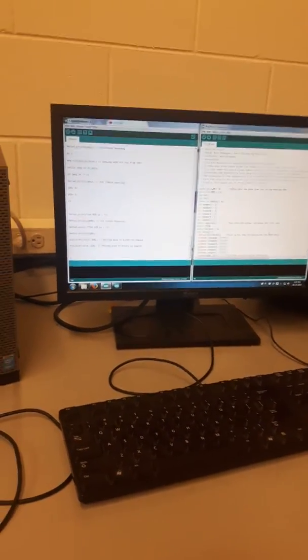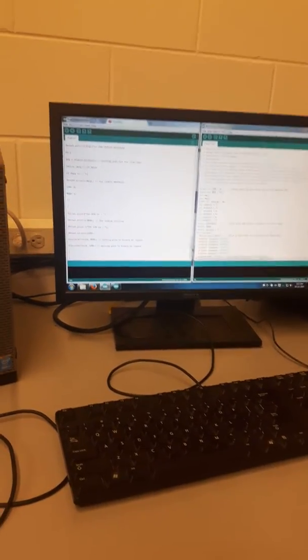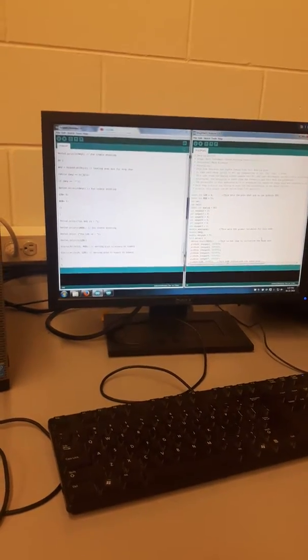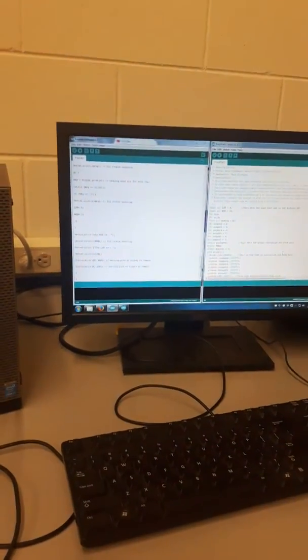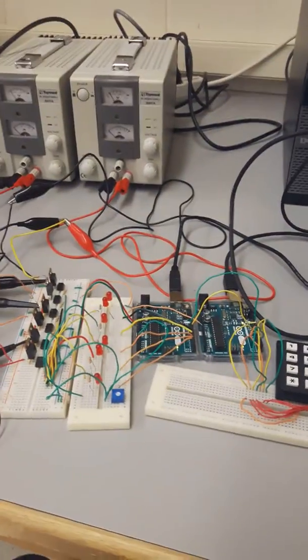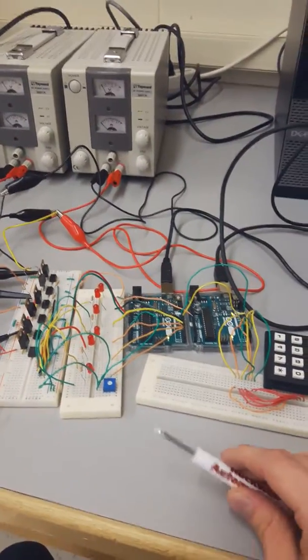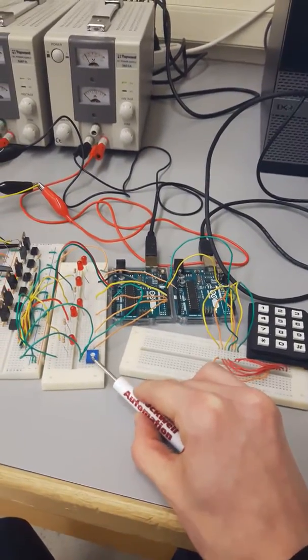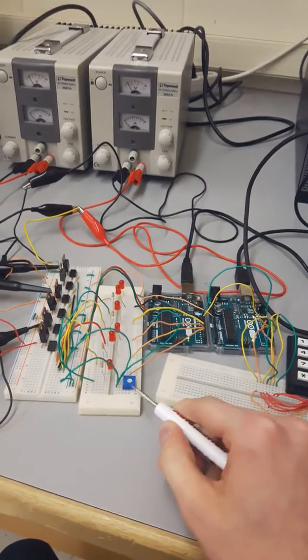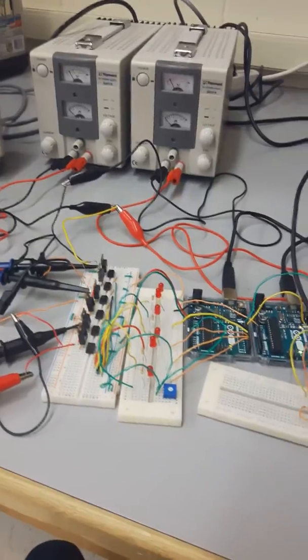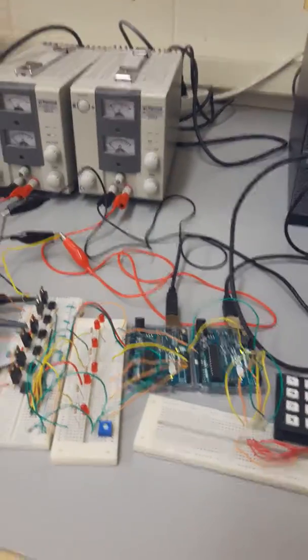This is Micro 2 project, the final project, part 2. This incorporates 3 steps: a keypad interface, a frequency interface that's also controlled, its duty cycle utilizing this potentiometer, and a power circuit to complete the 3-phase inverter.